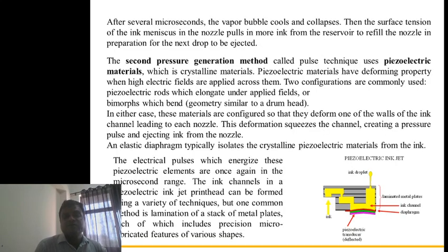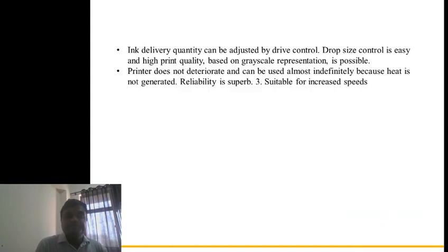In the piezoelectric pressure generation method, it is better than the thermal generation method because heat is not generated. Second, this deformation we have created regains its actual shape after some time. So the printer is not deteriorated, because whatever deformation we create can easily be removed, and again we can create deformation.